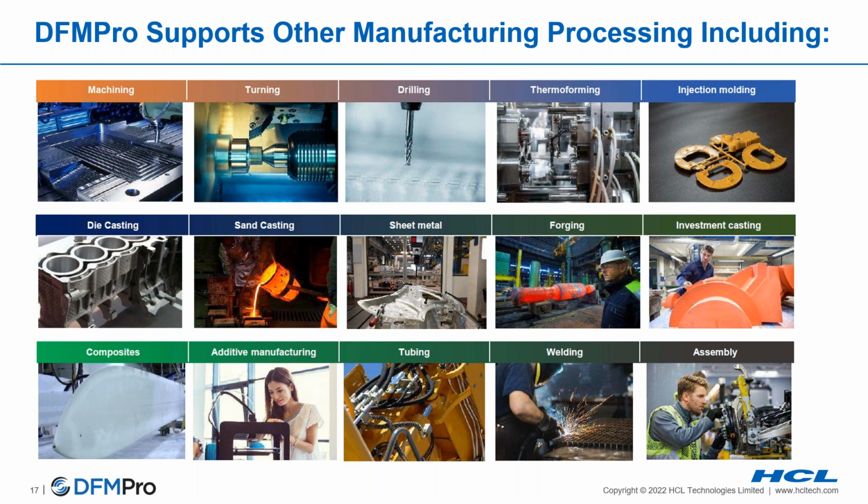Does DFMPro support PMI and have any rules on that? Yes, DFMPro rules support the PMI information. We have developed a couple of rules which use the PMI information available on the CAD. We have developed a geometrical tolerances rule and a dimension tolerances rule that depend upon the PMI. Yes, DFMPro supports the PMI information.